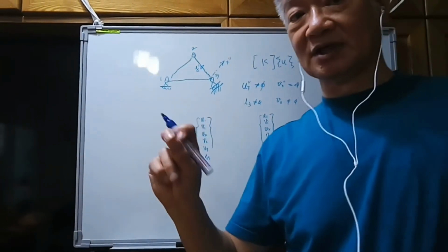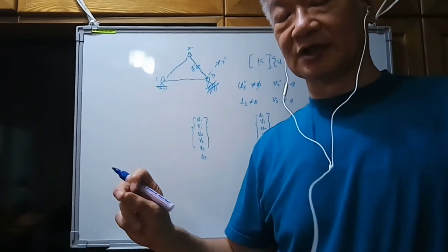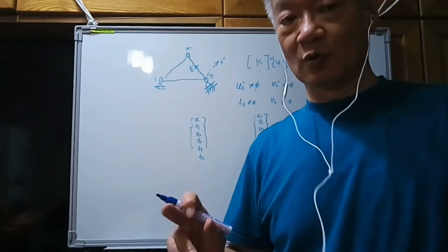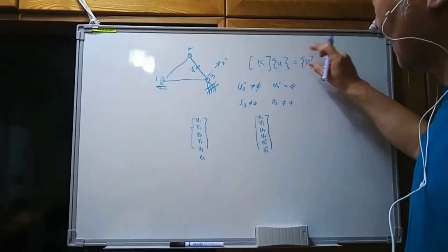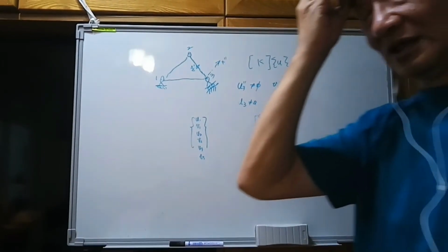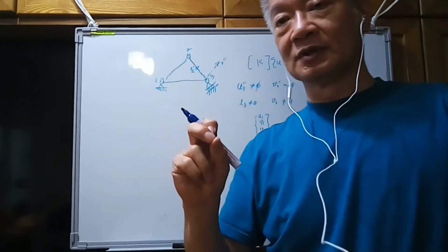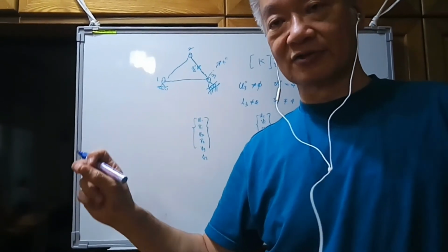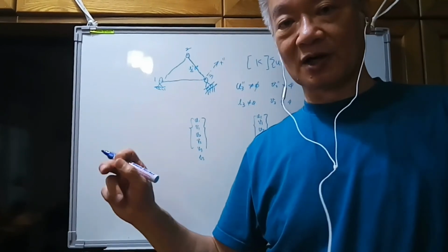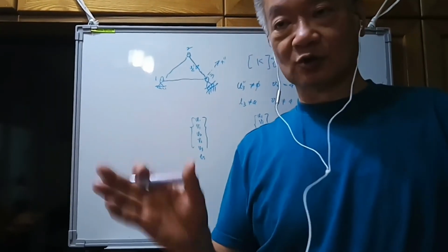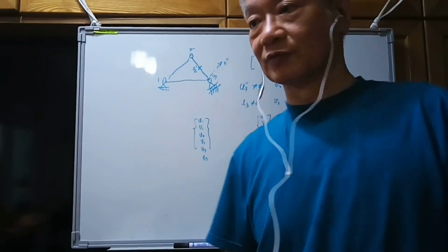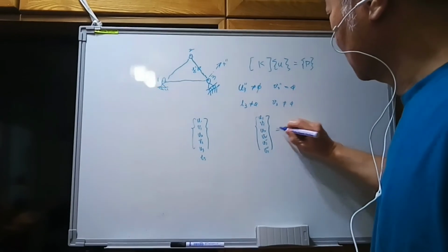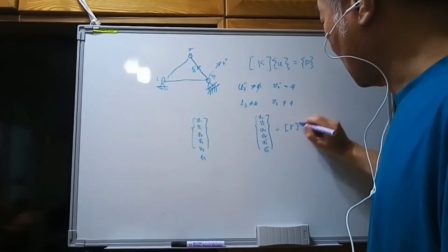And also the P vector. Originally we got the PX3, PY3. Both of them are along the global X and the global Y. But later I'd like to transform the vector components P to the PX double prime 3 and the PY double prime 3. Okay, the force components also I'd like to transform. And for this one, usually I need to use an R transpose.